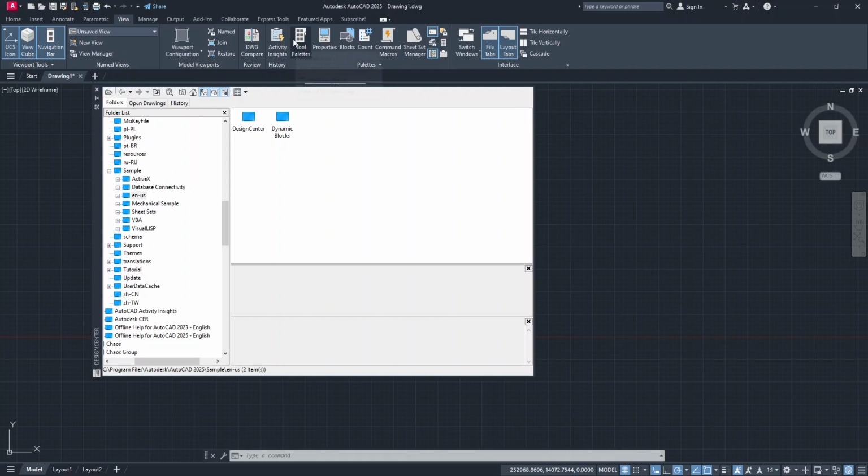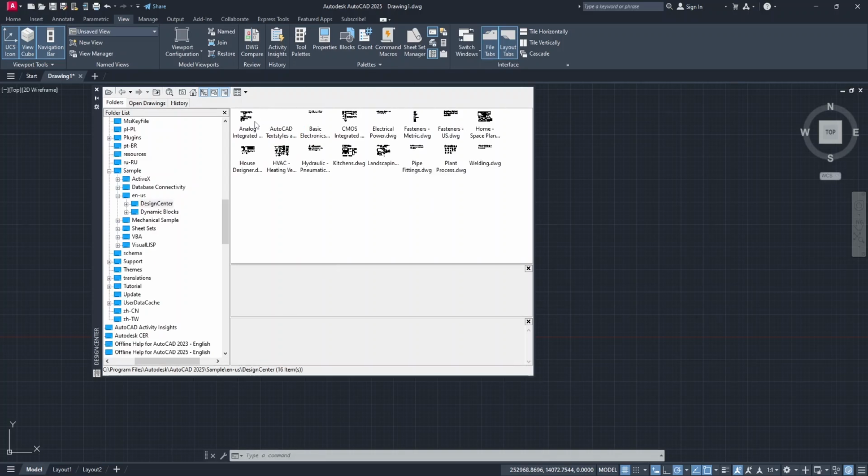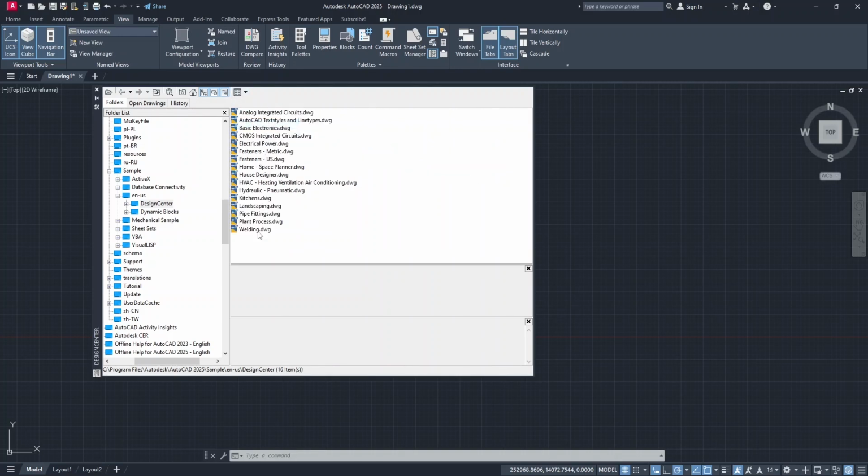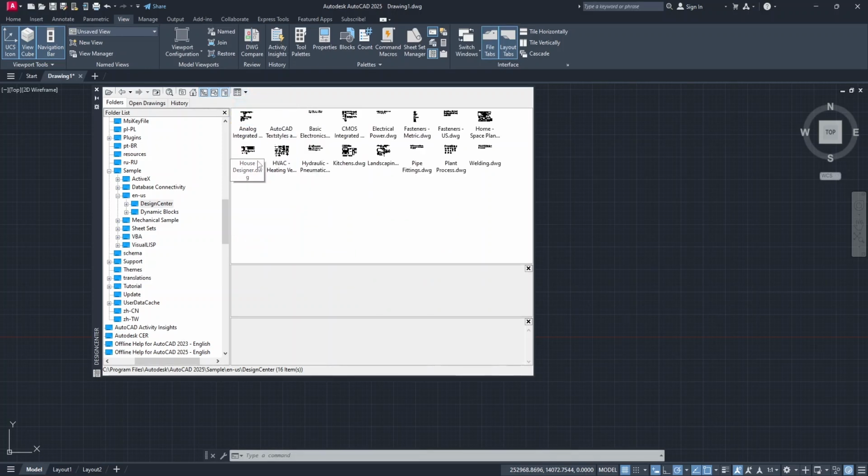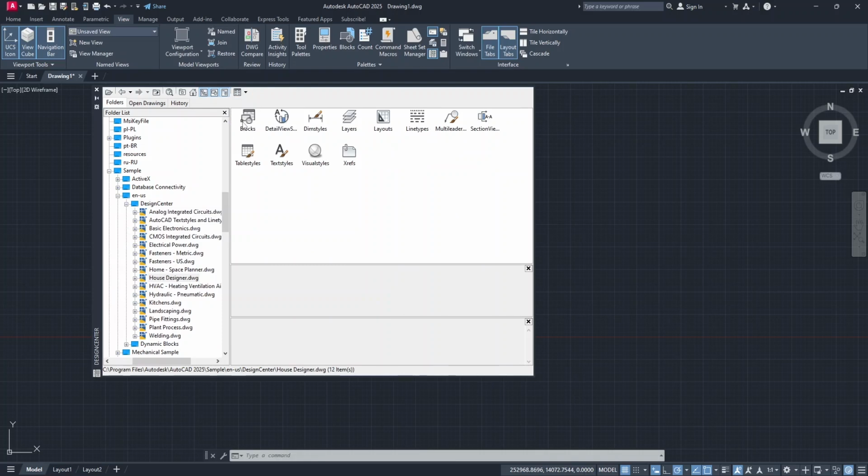That's why they are taken to the tool palette. Not all floor plans will have a bed or a sink. So click on Design Center and there are more files. These are regular DWG AutoCAD files, which if you list them, you can see them. They are regular DWG files. Click, select large. Let's enter house and see what's here.